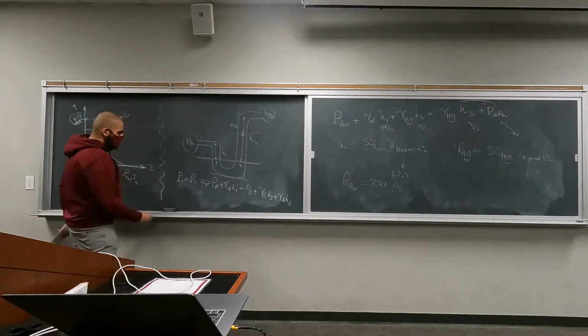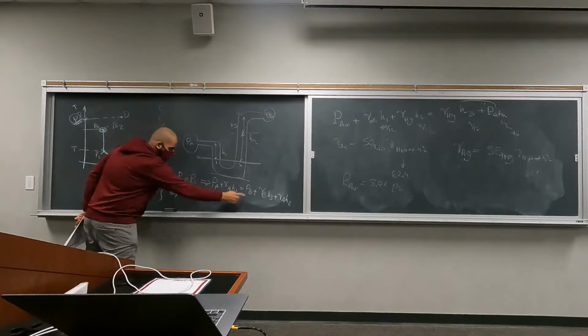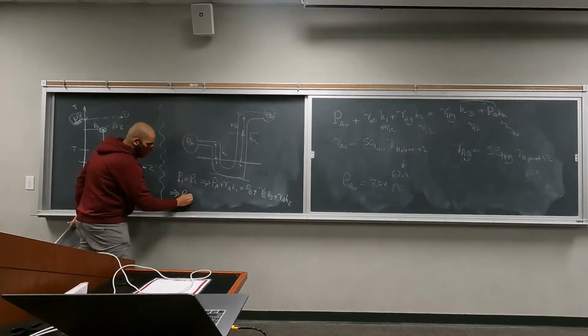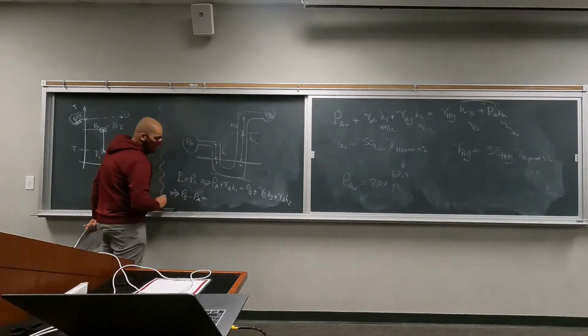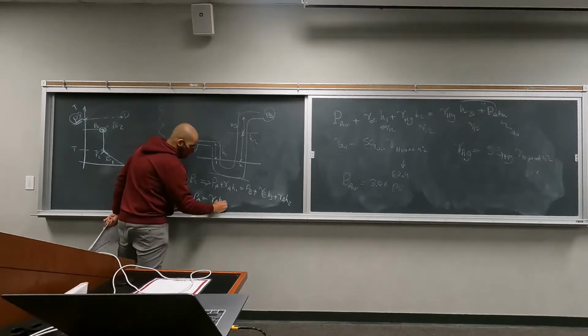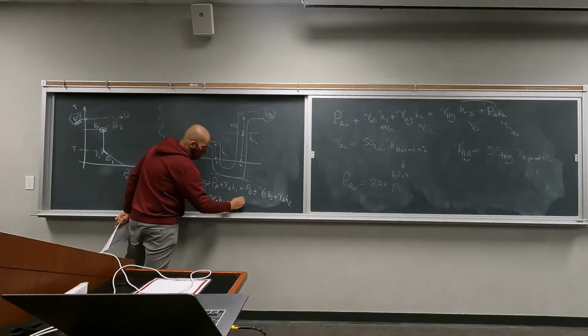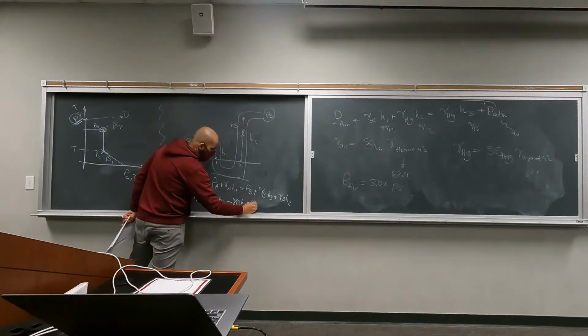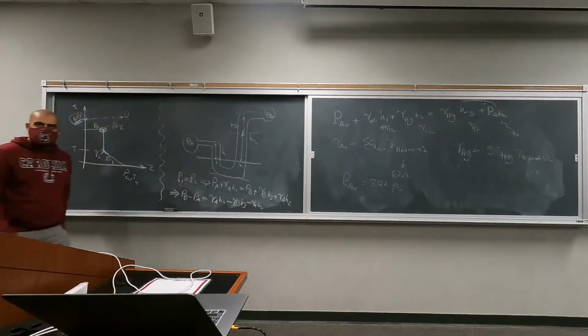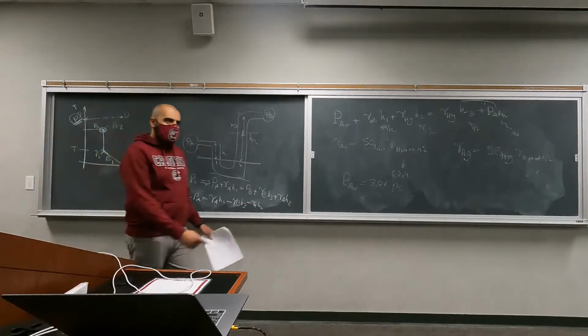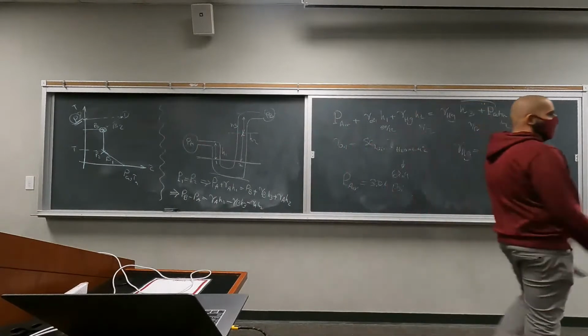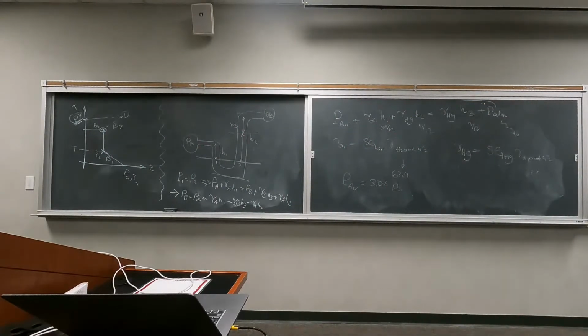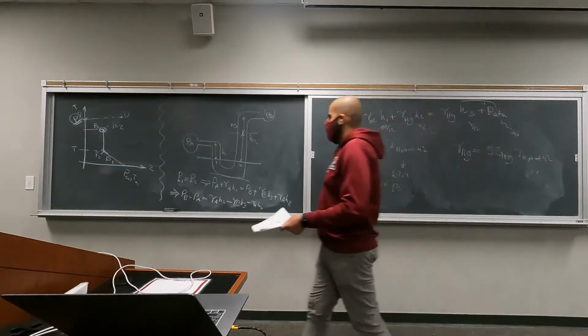If you are looking for PB minus PA, you can move things to the other side, rearrange, and this is what you are going to get. So the whole philosophy here is that in a U-tube manometer, 2 locations that have the same height and are made from the same liquid or gas are going to have the same pressure.